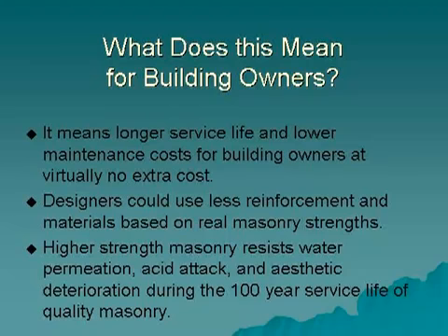Although not necessarily needed for structural purposes, architects and engineers should consider that higher strength masonry provides real performance benefits. To name a few, water permeation from wind-driven rain, acid attack, and aesthetic deterioration such as paint loss are greatly diminished with quality lightweight masonry walls made with lightweight block using expanded shale or clay lightweight aggregate.